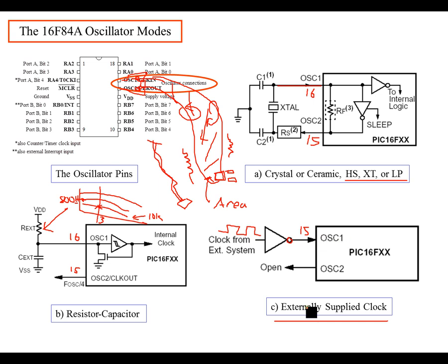And then again, you're going to have to configure all these things with the configuration word. The way you tell the chip what you want is with the configuration word, and then you set the hardware externally. You can't just set it however you want and then turn on the chip. It's not going to work. You have to set the configuration word in order for it to work.